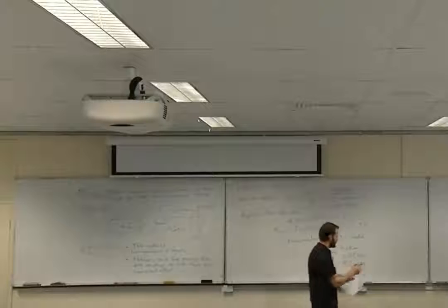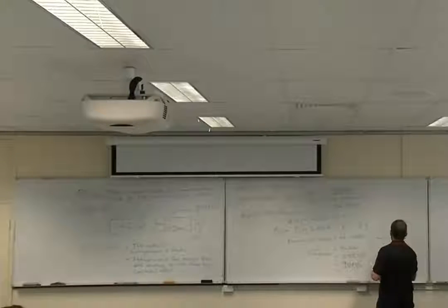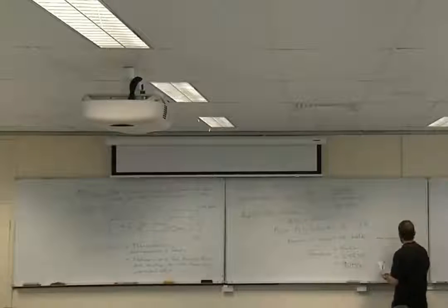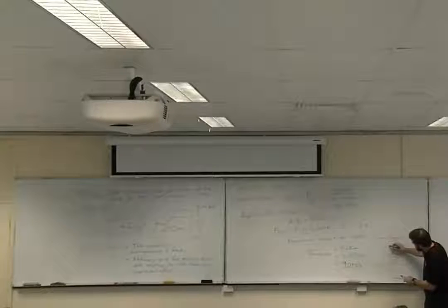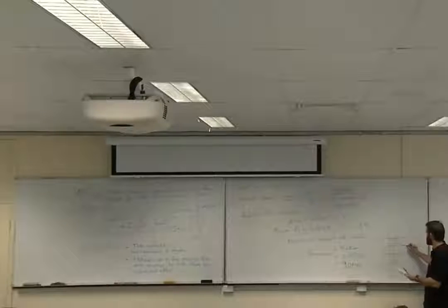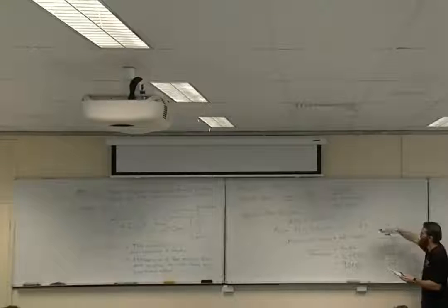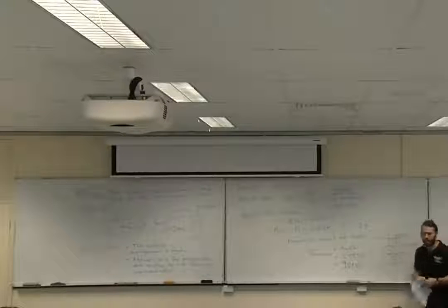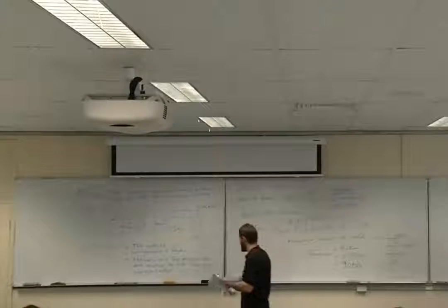Then what I did was draw this, and you can draw your stress profile looking like that, just so you know what it looks like. Your maximum is either at the top or the bottom there. This value here is going to be 90 megapascals, and this value is our normal stress, 36 megapascals. So you can see the hole makes a significant difference here.